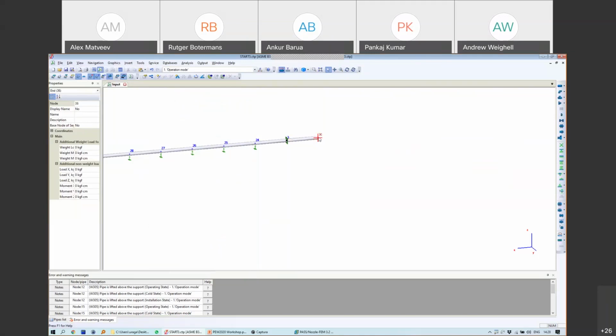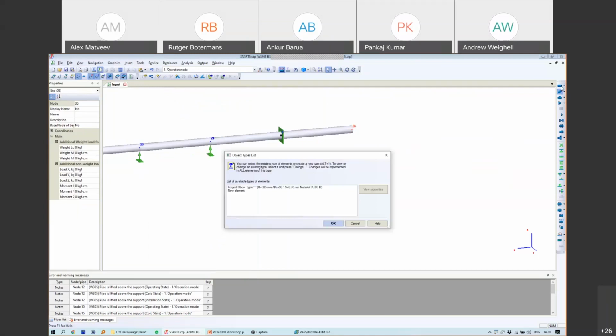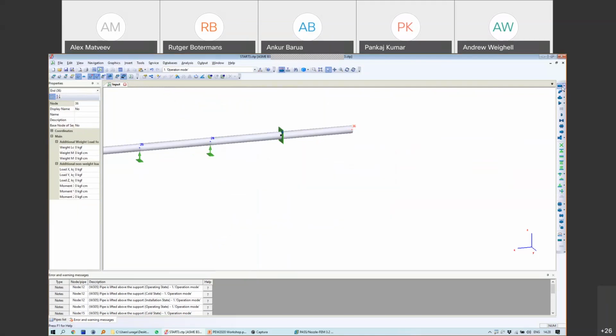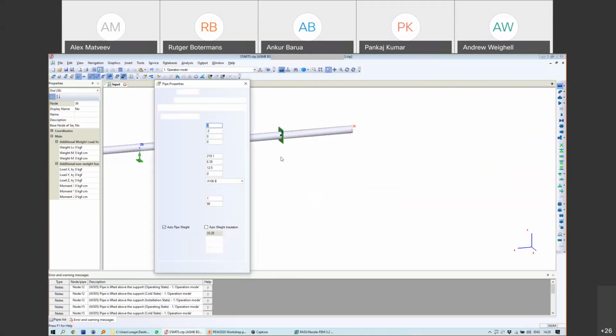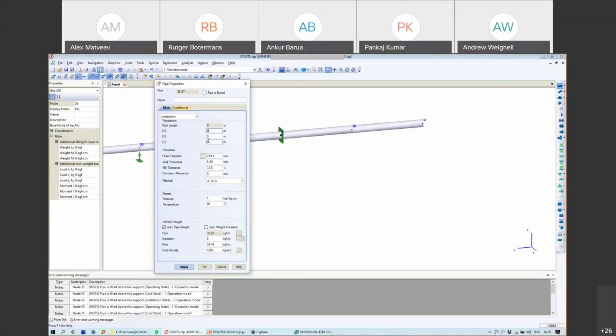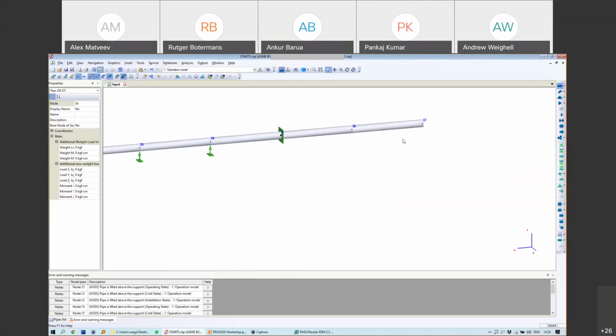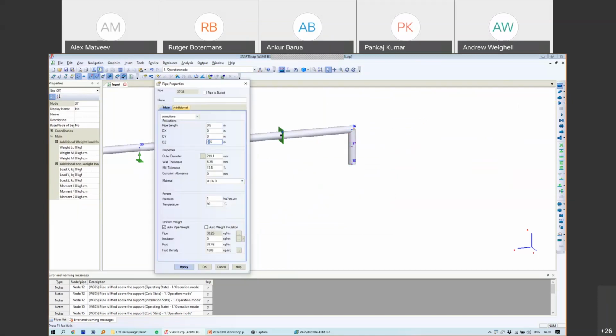Okay, we have a 2 meter pipe, and now it will go down underground. I will add the next pipe in minus 0.5 meters. This will be the entry point underground. Now I add the underground pipe, 1.5 meters, and I check this checkbox, pipe is buried.